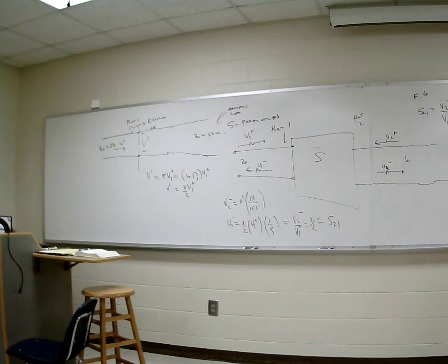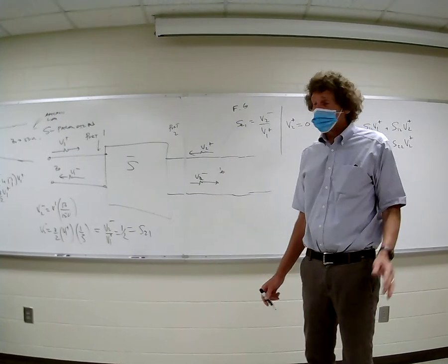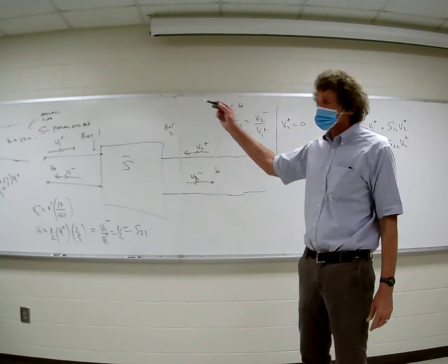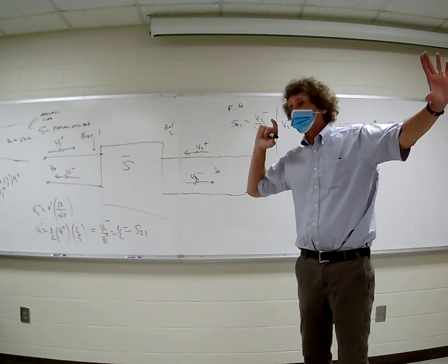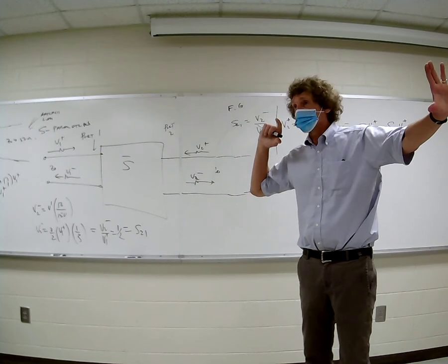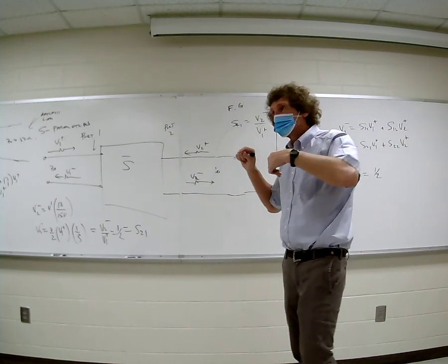This is in the book. I want to make sure you see this. This is the way we get the forward gain. So whatever's coming in, half of it comes out as far as voltage. Y'all follow me? How many see that that would be the same thing for S12, the reverse gain? Output voltage versus input voltage. You better believe it. It's symmetric, isn't it, class? So that's how you use these S parameters.